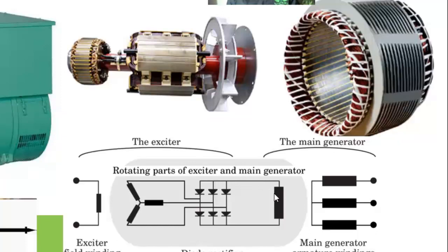So now you see this winding. Like we said before, this winding does not have any interaction with the yoke. So when you probe the terminal, okay, you disconnect the winding leads from the exciter, from the diode plate.